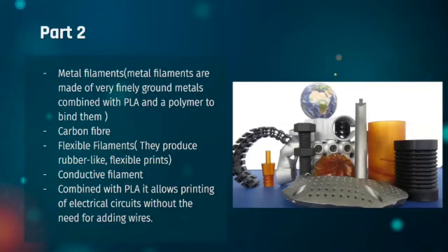There are more materials, some metal filaments. However, even though these may be named metal, it won't be as heavy and as strong as solid metal, and it won't weigh as much. These metal particles are bound by plastic and glue and will not conduct electricity. These are good for printing metal sculptures and figurines.